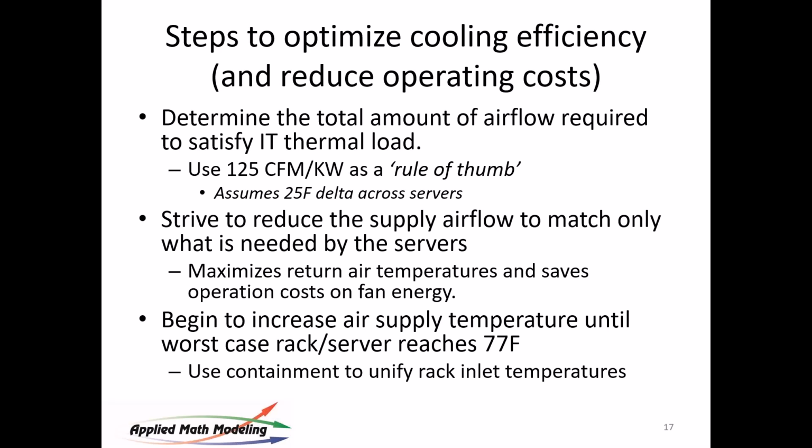Maybe I can add something there. We just updated our training program, and we found that this effect of the fans in the server speeding up is almost marginal compared to the savings on the chiller side. It's almost a factor of 10 difference. So we shouldn't be too concerned about that, actually. Okay, that's good feedback. It goes to the point of, hotter is better, really.